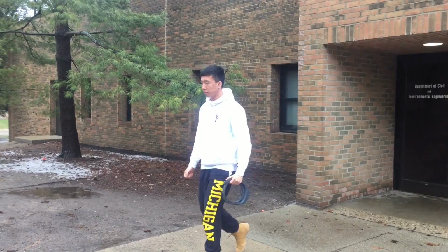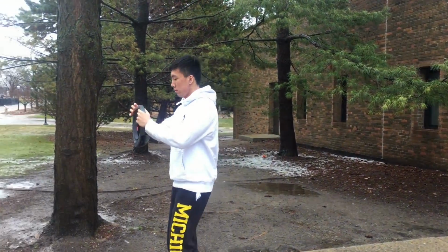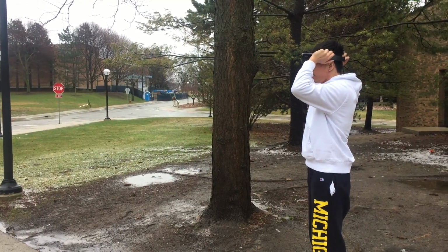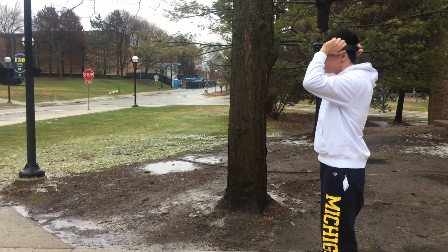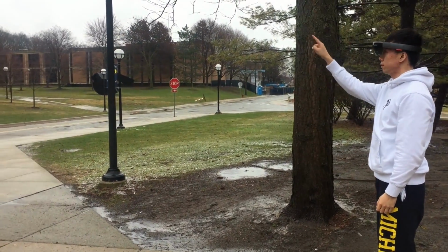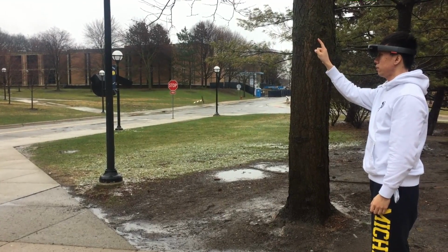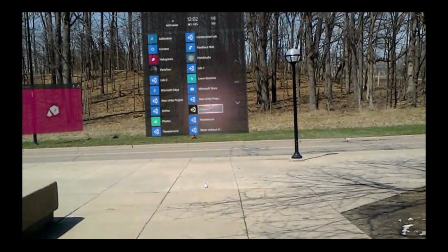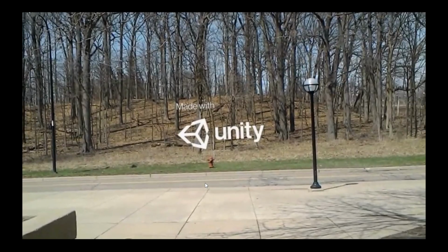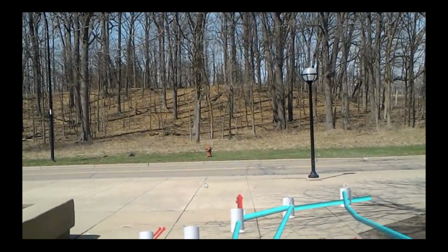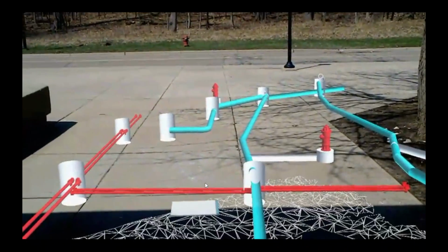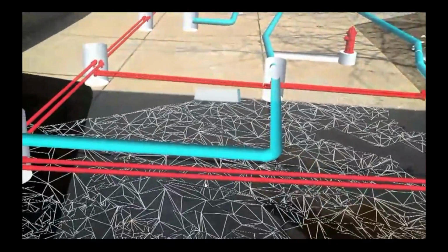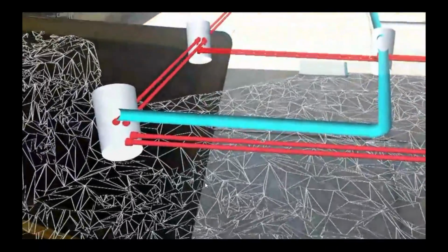Once you finish the above operation, next time the construction manager just needs to carry HoloLens and enter the construction site. Deploying the HoloLens, superimpose the models, and it could easily observe the underground utilities for a long time. Besides, our models can be georeferenced in the real-world scale. Once we get enough underground utility data from ArcGIS, we could create as many models as we want.